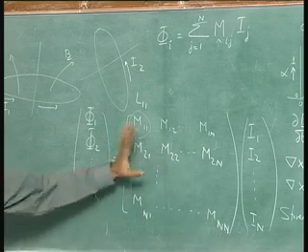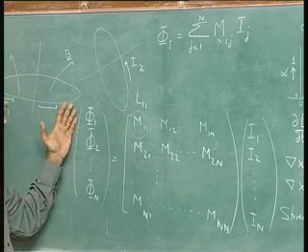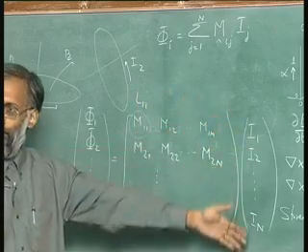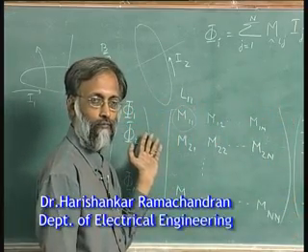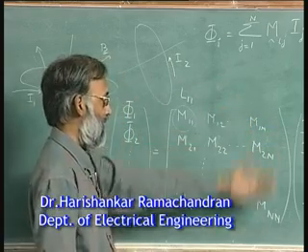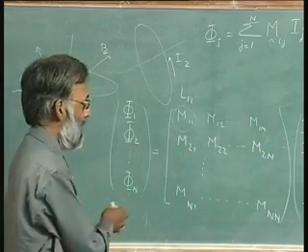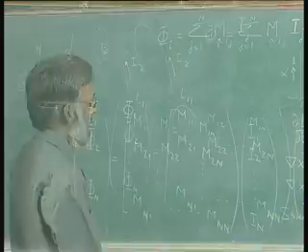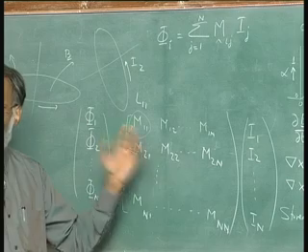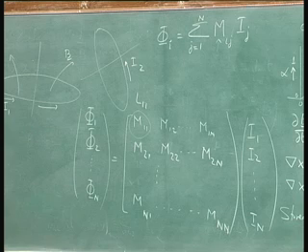But if I know these numbers, then calculating flux is just matrix multiplication with currents, and calculating currents given flux is just inversion. I can just take the inverse of this matrix multiplied by the fluxes and it gives me currents. It is also easily provable that this matrix is always invertible. They are physical things, therefore, you cannot have a non-invertible mutual inductance matrix.